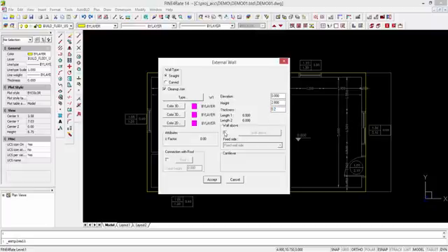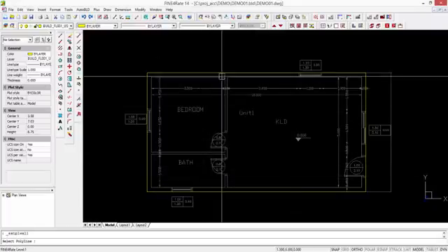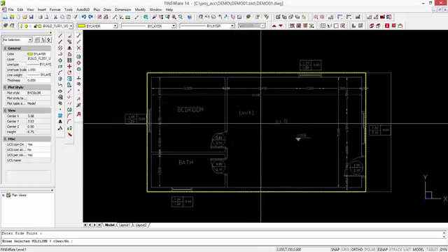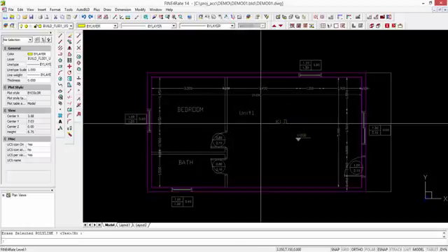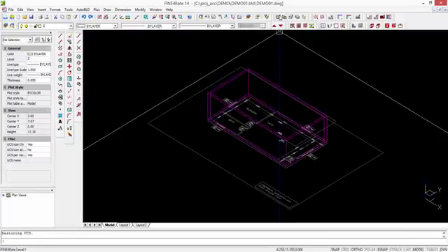And here, if I had a double wall, I could use the wall above feature. So by clicking accept and selecting the polyline, I just enter the side point and right click, and as you can see, I already have the external wall.